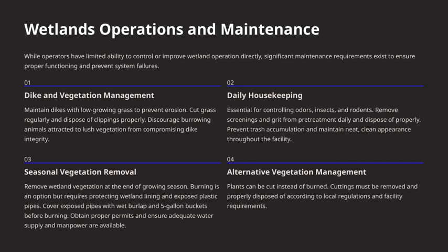the dikes. Next, daily housekeeping is vital. This helps control odors, insects, and rodents. Every day, we should remove screenings and grit from pretreatment areas and dispose of them properly. Keeping the facility neat and clean by preventing trash buildup is also a key part of daily maintenance.